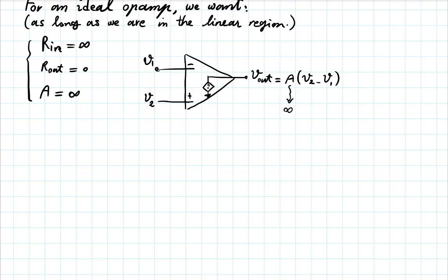In fact, this is perhaps a key beauty of the op-amp: what you do with it typically only uses the quality that it has a very high gain. It doesn't care much about what the gain is exactly, or what the variations may be with temperature, because the primary function just relies on having a very high gain. The rest of the job is done by everything else that you connect to the circuit, and we'll see examples of that in a minute.